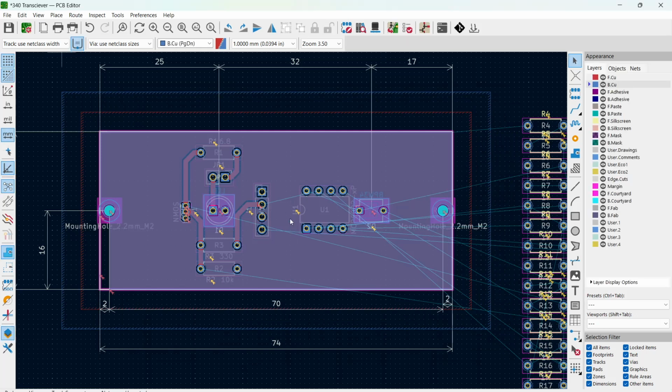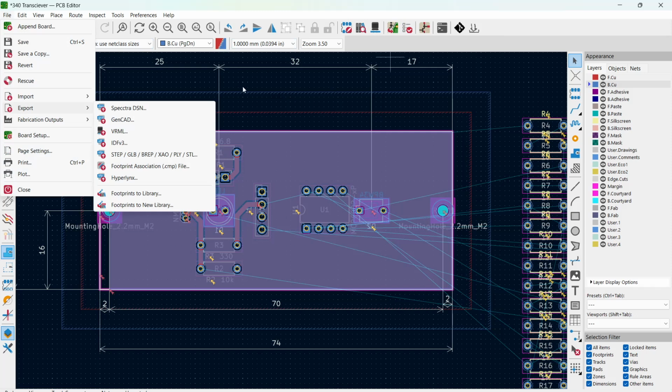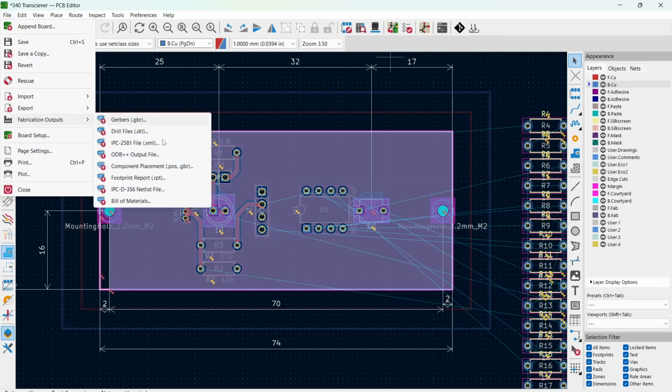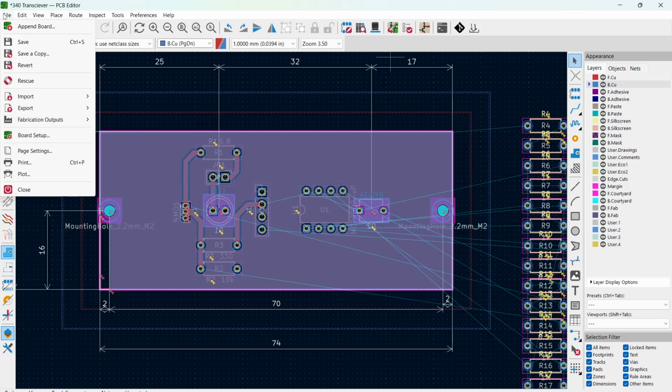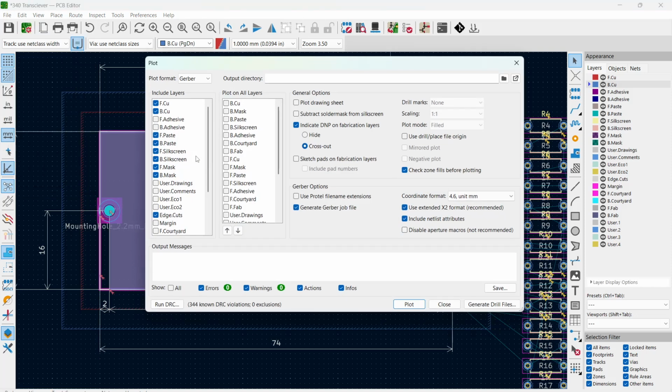And from this point, you'll want to actually generate your fabrication outputs. I recommend running your design rule constraints long before doing this to make sure you're within those. And you can do that here. But we will also do it in generating the fabrication outputs. And if you can't see already, this PCB is not done, but the process will be the same once it's finished. So you'll come over here to File, go down to Fabrication Outputs, and click on Gerbers.